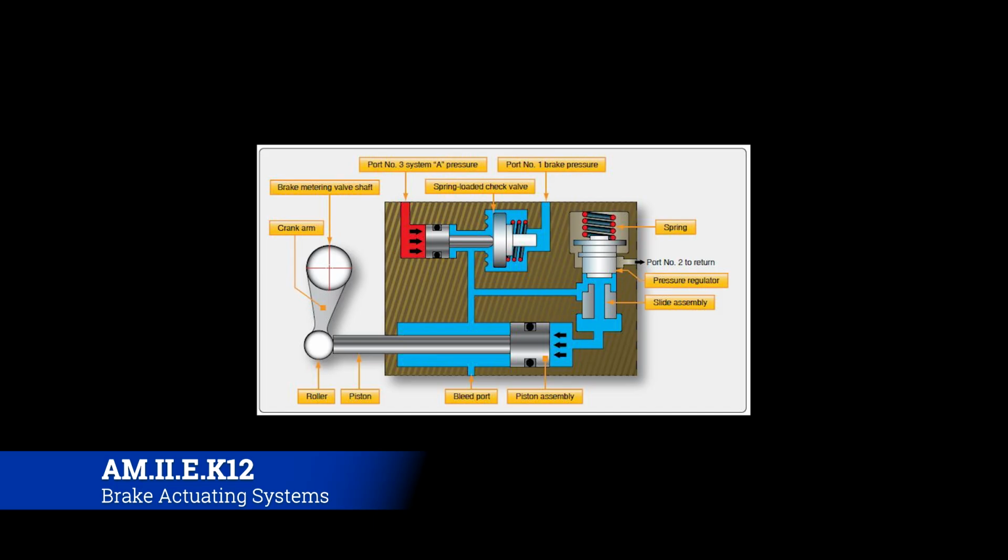Now, if we look at the top, we have cable brake systems that control your valves, as opposed to electronically. Then there are a couple of other things I want to bring to your attention that we covered in hydraulics that have now found their place in the braking system, primarily the shuttle valve, like we just talked about, and the fuse. There's a hydraulic fuse on the top right-hand side. If you've forgotten what fuses are, go back and review, because that's a place you could potentially find a hydraulic fuse.